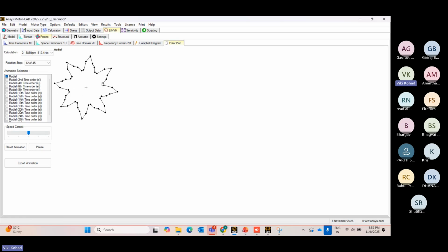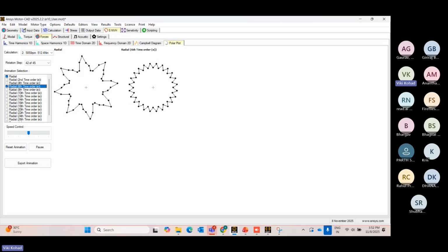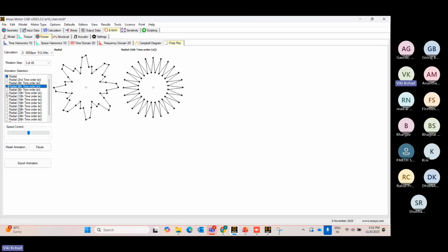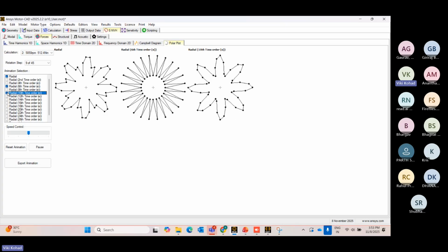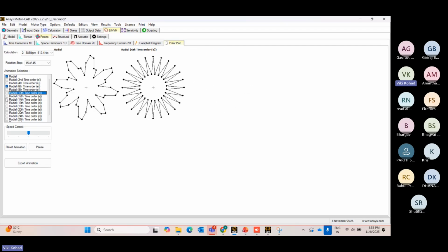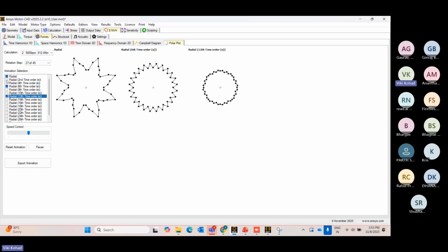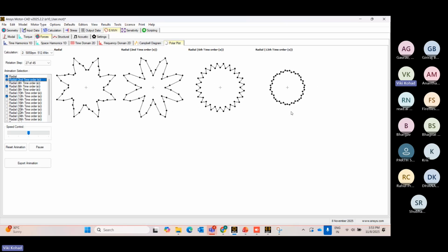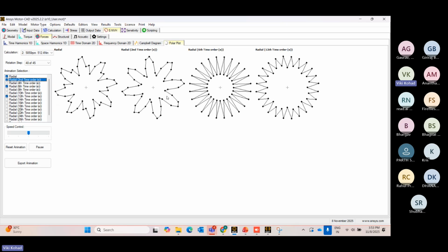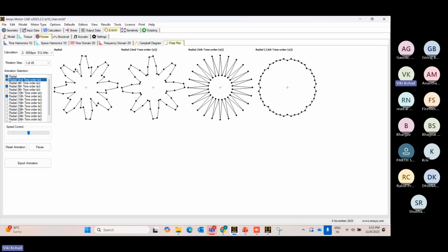It shows the excitations that are applied by the radial forces, how the radial forces are applying the excitation on the stator part. You can see this on the 6th order also, on the 10th order, the 12th order. Now you can see the patterns are there, the second also. These are the orders you can see: this is for the second order, 6th order and the 12th order.